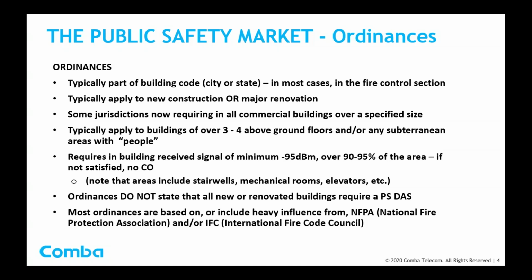You read that to mean parking, underground office space, underground retail. Ordinances typically require in-building signal receive signal strength of a minimum of negative 95 dBm, or decibels per milliwatt. They generally want coverage over 95% of the area. And if they don't satisfy those requirements, they don't issue a certificate of occupancy and the building owner can't move in. And note that these areas typically include stairwells, mechanical rooms, elevators, places that typically on a cellular DAS no one cares about.